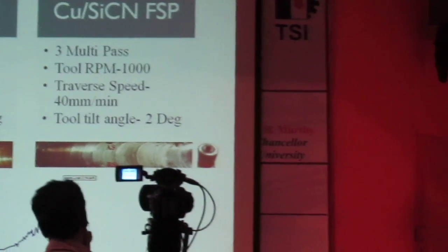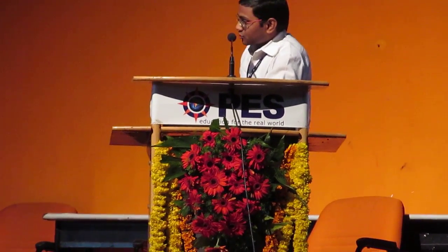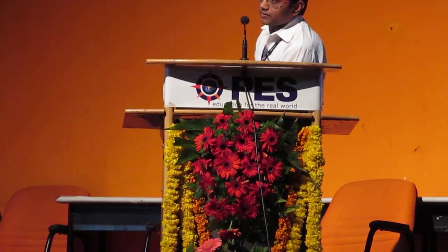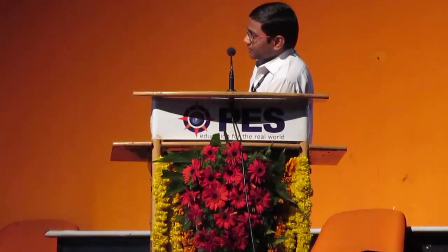And after processing, this is the image of pure copper processing, and this is the image of composite processing. And this is the load with time, how the load varies with time. So when the tool goes inside, there will be a low load, but when the shoulder touches the surface of the material, there will be a high load. After that, when it traverses, it will be constant. After that, it will drop.